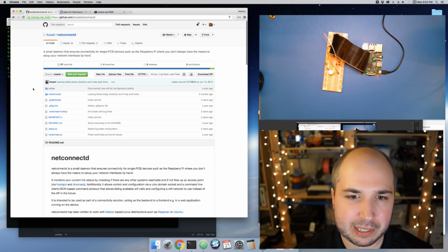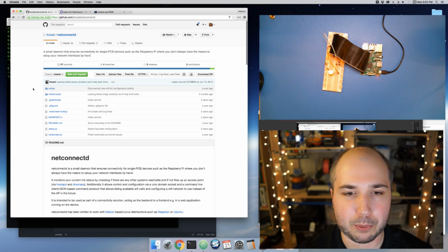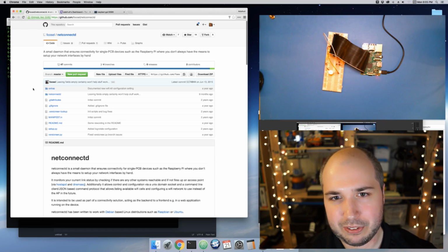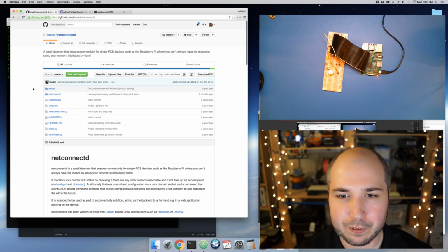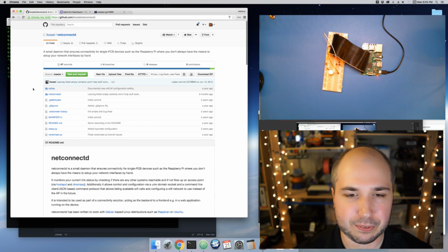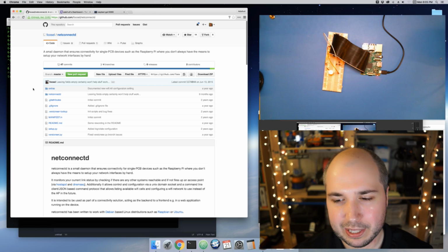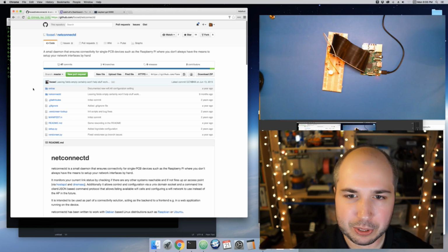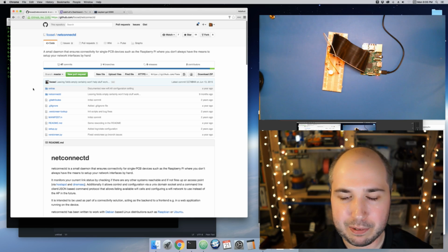And just the one big gotcha that tripped me up for a while earlier today when I was trying this out on the Pi 3 and even the normal Raspberry Pis, though they don't normally have a Wi-Fi adapter built in. I had to make sure to comment out that wlan0 configuration in the /etc/network/interfaces file. If I didn't do that, I noticed that on boot it wouldn't run. I couldn't see my hostapd firing up.